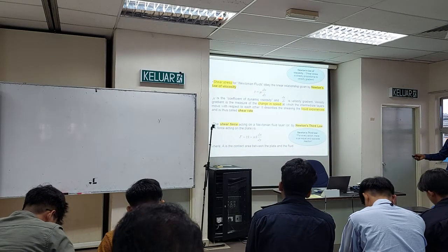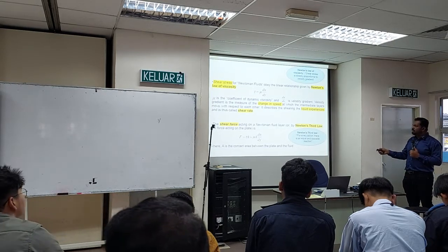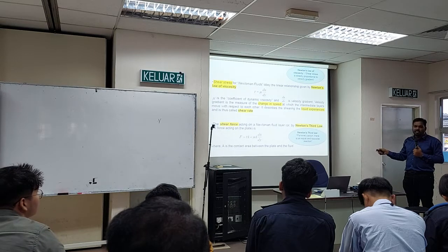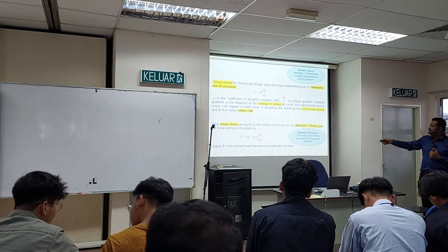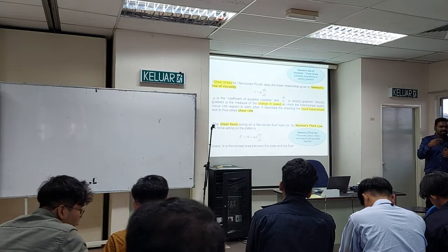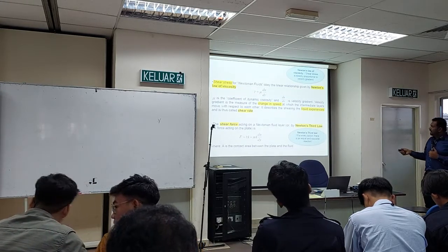Okay, so coefficient of dynamic viscosity. So tau equals to mu du over dy. Okay, this is another formula that you need to remember. So highlight lah formula ni, that you will use in your question. Okay, so you boleh baca lah yang ni.